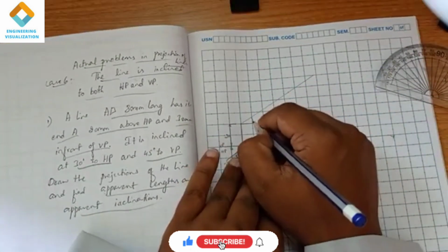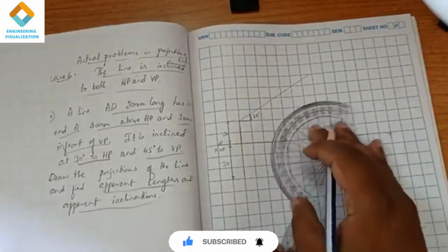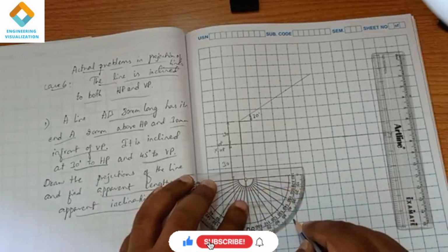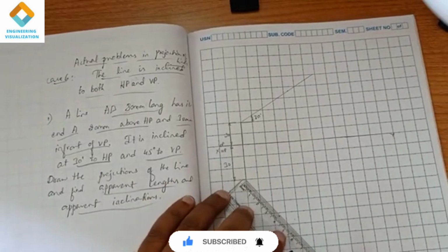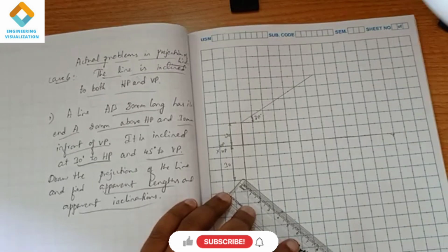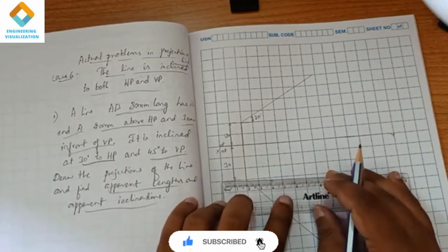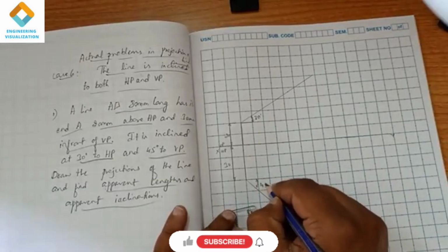So it has an angle of 30 degrees. Similarly, you have to mark 45 degrees to VP, and draw a line of length again 80. Here we can show the angle: this is 45 degrees to VP.